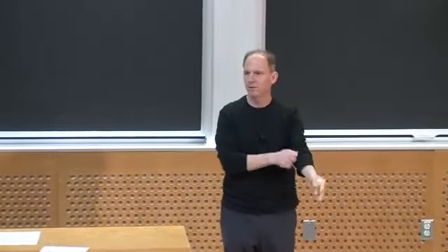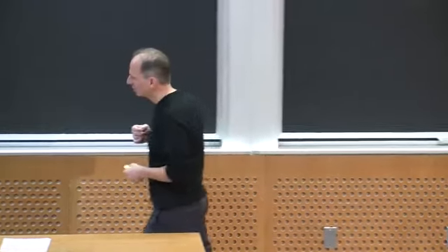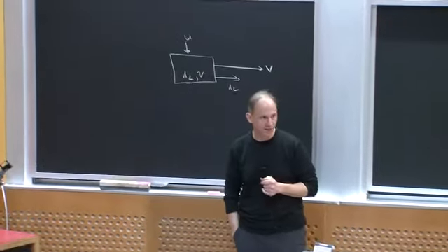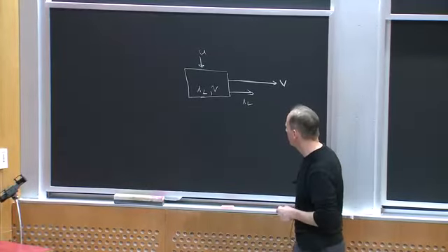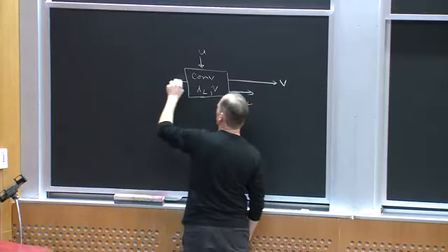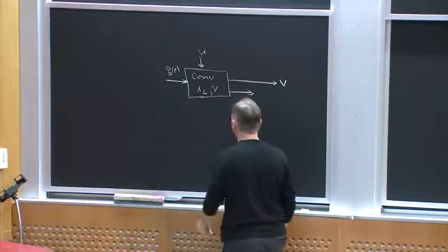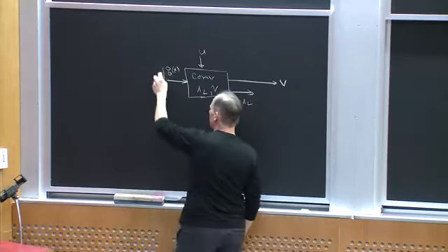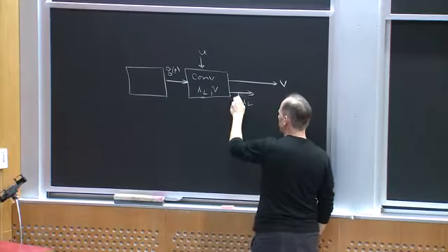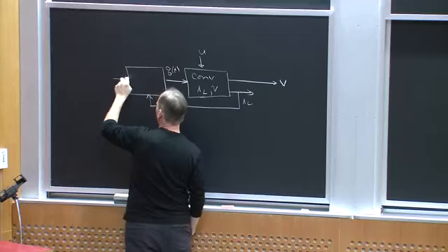I'm telling you about what's probably the most popular one in DC to DC converters, if you go out to buy one or to design one. A lot of the control chips use this technique. And here's the idea. For the converter, we said the input was, ultimately, Q of T. It's what's modulating the converter. Maybe I can say, let me feed back the inductor current and compare that to a reference.